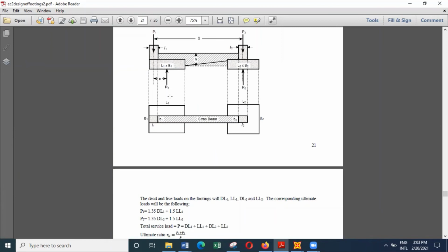And in addition to that, this footing will need top reinforcement as well. This footing will need mostly the bottom reinforcement. But because these are important structural systems, if you want, you can provide some nominal reinforcement at the top of this footing. And this way, the bending moment is not that critical because this footing is supported by the strap footing. So in this direction at the bottom, you will be able to provide nominal reinforcement.